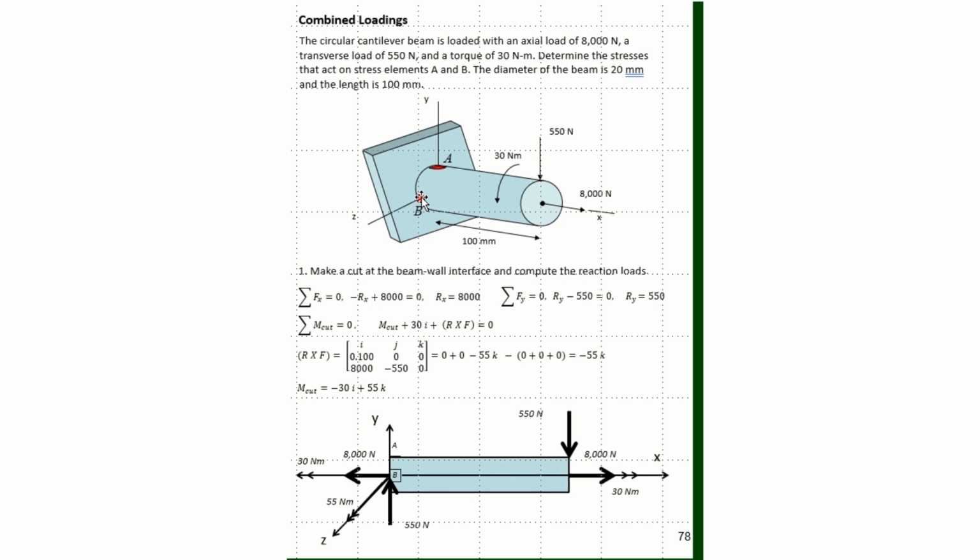So we know the steps to this are to draw a free body diagram of the structure, label a coordinate system, and draw on the reaction forces and moments. In some situations, we will need to use shear moment diagrams to determine the critical location. But in this cantilever beam example, we know the critical location is at the wall.